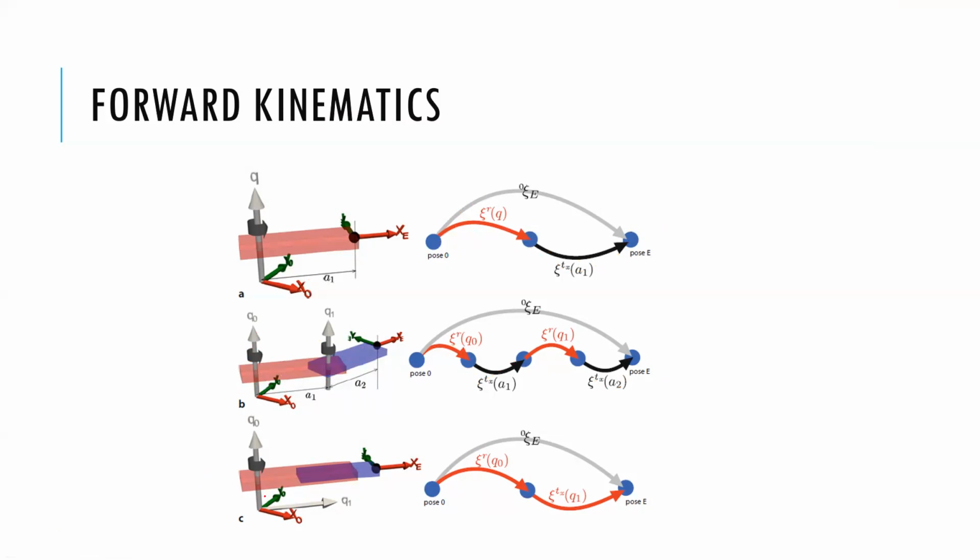This guy here is a rotation, and this is prismatic, meaning this slides up and down. So the length of this varies. I see a rotation, and then this other joint is a translation component because the length is variable. And a robotic system is usually a combination, a mix and match between these different configurations.